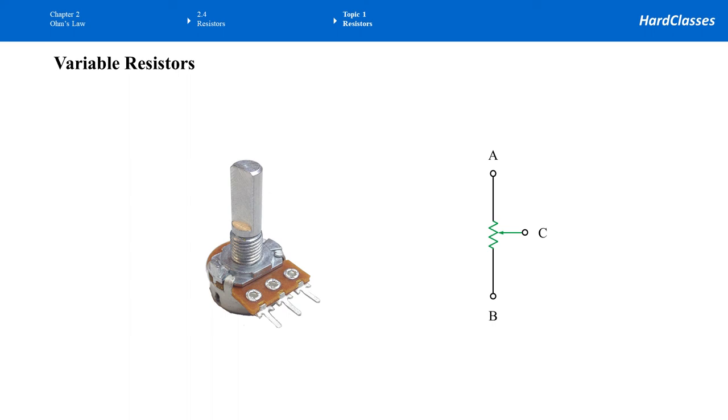To use the variable resistor feature, we just need to use the center terminal and the terminal on a side, such as B. If we select terminal B, and terminal C is like the schematic symbol, moving terminal C upward, as you can see, we are using more green region, so the resistance value increases.